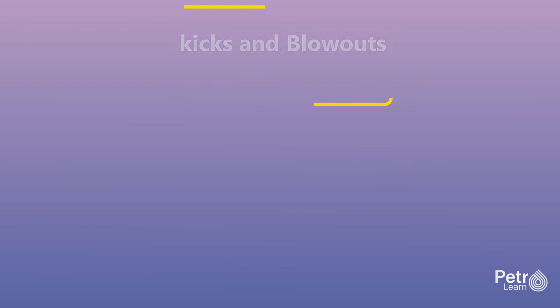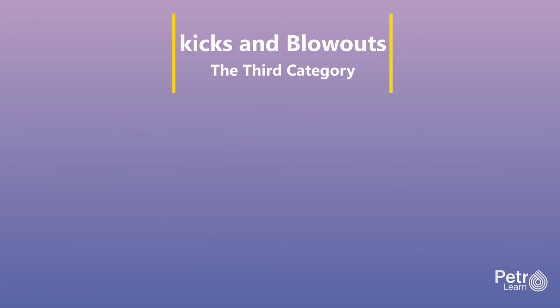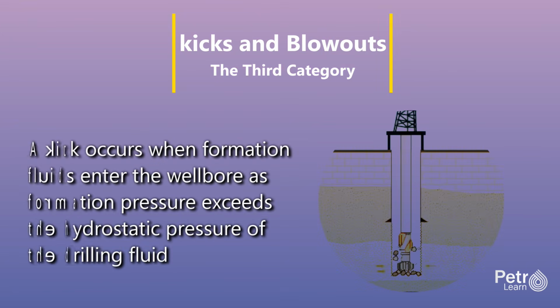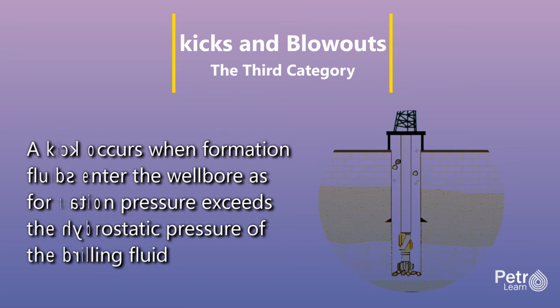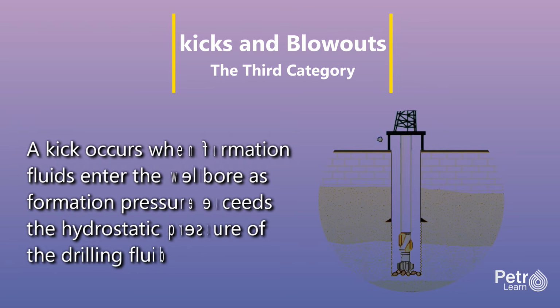The third critical problem is kicks and blowouts. A kick occurs when formation fluids, oil, gas, or water, enter the wellbore because formation pressure exceeds the hydrostatic pressure of the drilling fluid. Kicks are dangerous because they can escalate into blowouts, which are uncontrolled flows of formation fluids to the surface. Blowouts can result in fires, explosions, environmental damage, loss of life, and destruction of the rig.